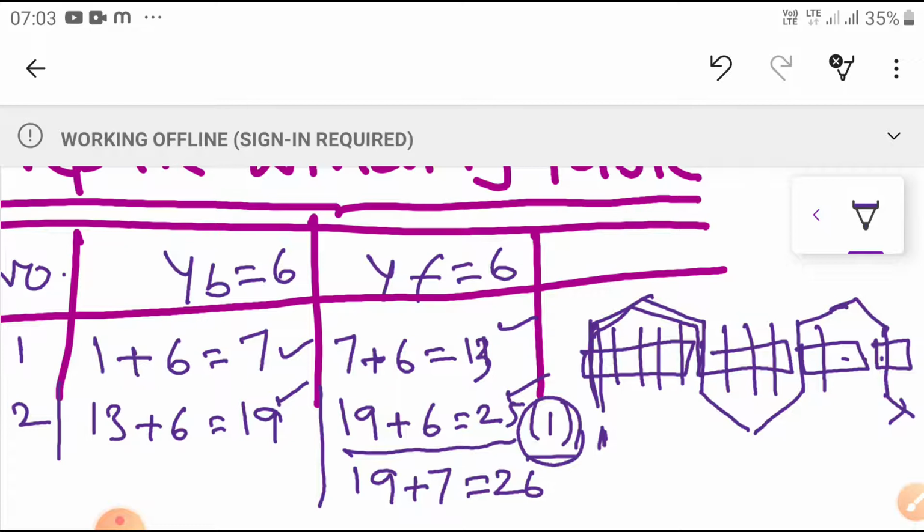Okay. Then what to do? For that purpose, you add 1 and place the coil side at slot number 2. Adding 6 plus 1 is 7, and 19 plus 7, we are going to get 26. Since we have only 24 slots, 26 minus 24, we are going to get 2. So that means this end we are going to connect to the second conductor in the second slot.